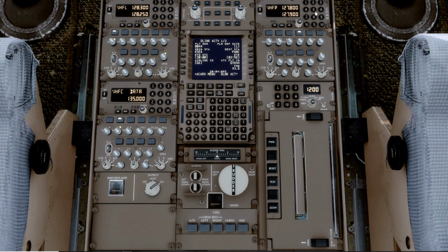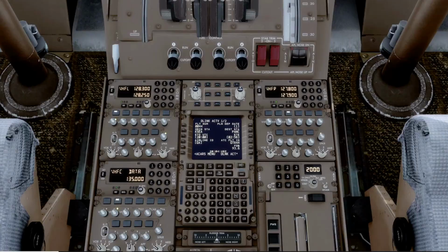Again, right radio tuning panel can be tuned to ATIS or whatever we need. And then my audio panel, I can go to the left or whatever I want to do. If I'm going to get the clearance, maybe I go to right. Speaker, whatever. Transponder, we'll go to 2000, which is VFR. Once we get the clearance, then we'll put that in, make sure this is on standby, and we're on left transponder, that's fine. And we're on N for the normal range of altitudes, what it's looking for in terms of the TCAS system. And then we'll adjust our seat and adjust our rudder pedals, and that's kind of it for the FO.